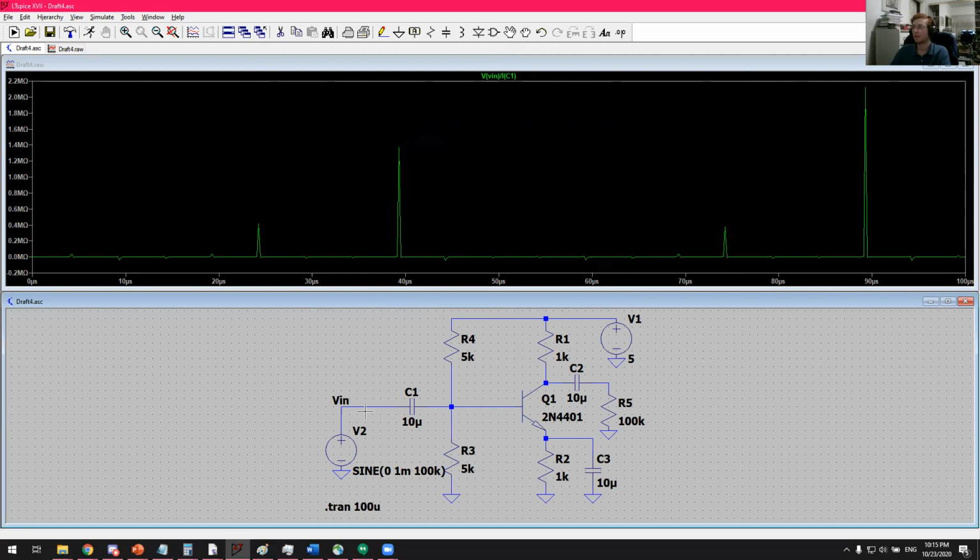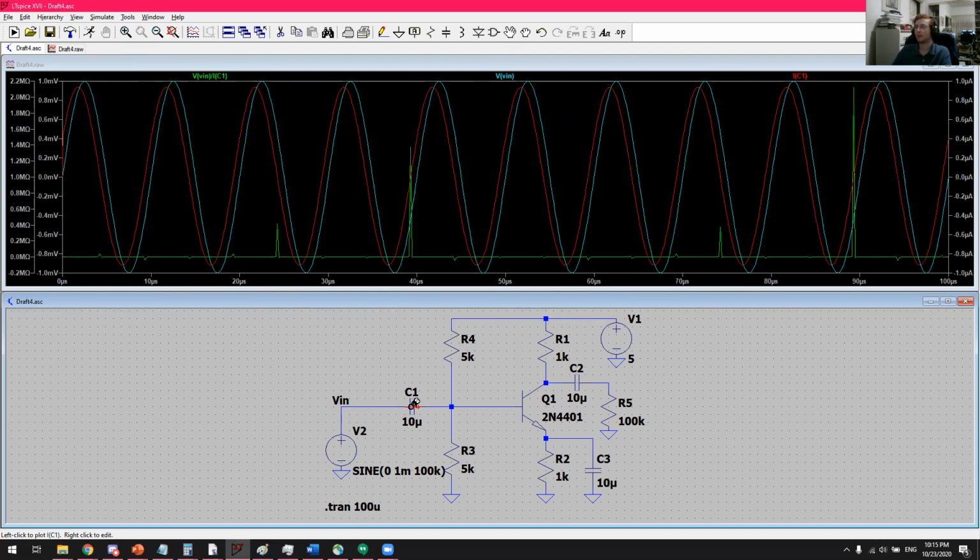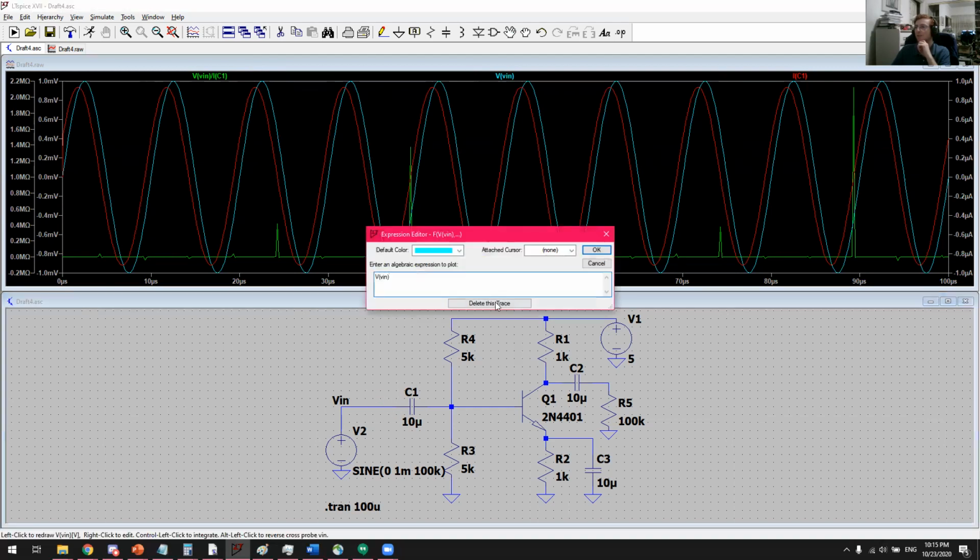And here we go. So this is the problem with transient simulation. So I have to use a different type of simulation here. You'll notice that the problem here is that I'm taking a sinusoid divided by another sinusoid that are not necessarily in phase, and that could result in dividing by 0 or other mathematical problems. What I really want to do is take the amplitude of one of the sinusoids and divide by the amplitude of the other. So let me fix that. Let me delete these two traces.